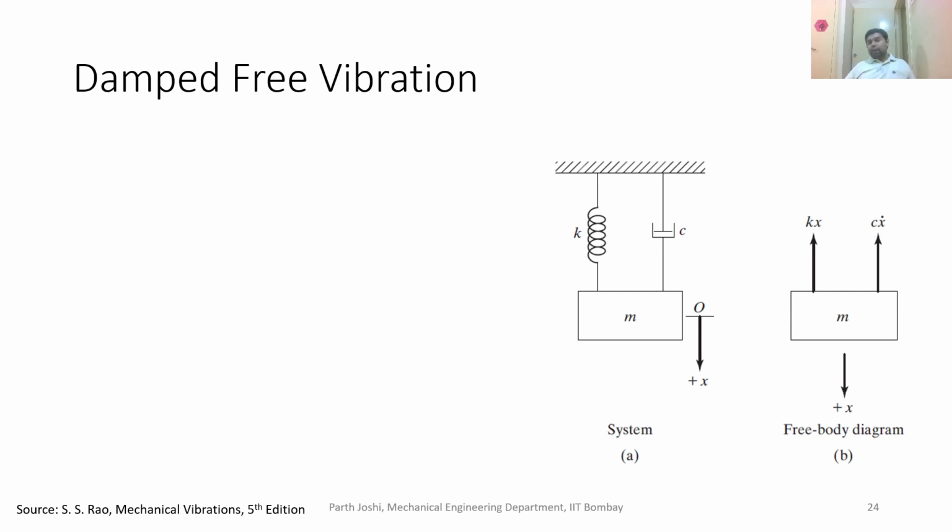Now whether that is viscous damping or other kinds of damping like Coulomb damping, because of what is called Coulomb friction, which is because of rubbing of two different surfaces, that will also cause some friction. Viscous friction is basically when we have interaction between the surface and the fluid. So this is a model which is called a lumped parameter model, as I said. It will represent it as a spring mass and damper system.